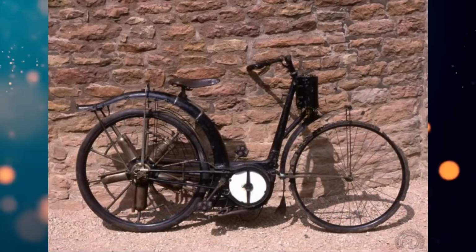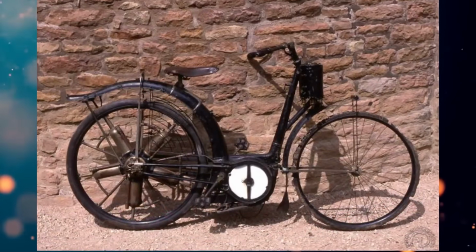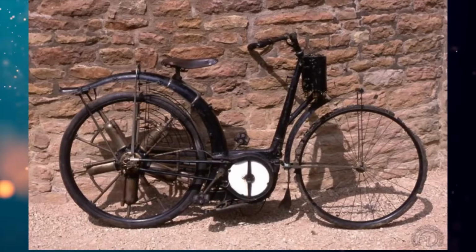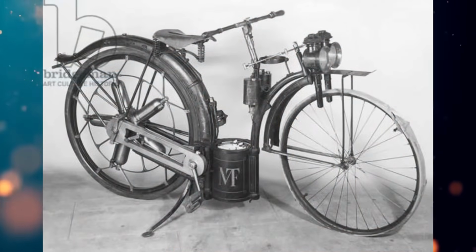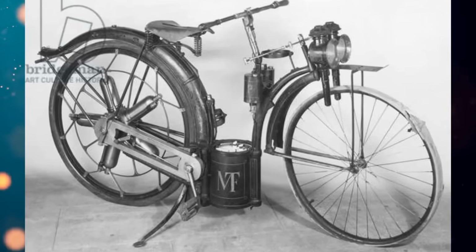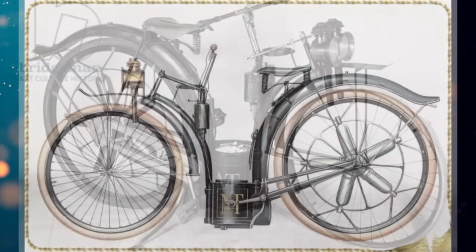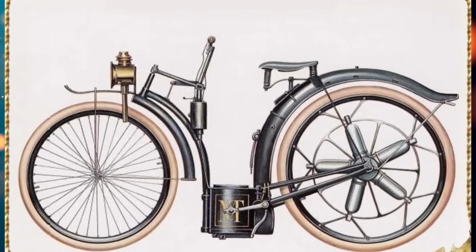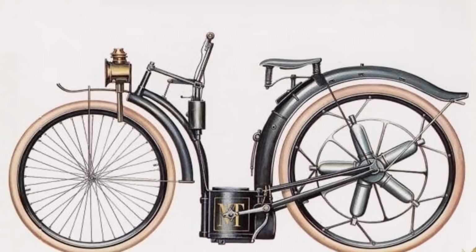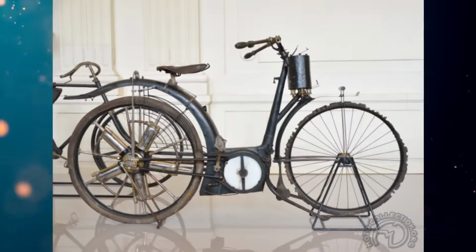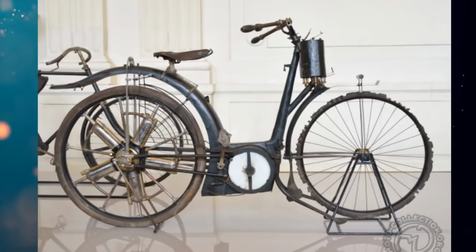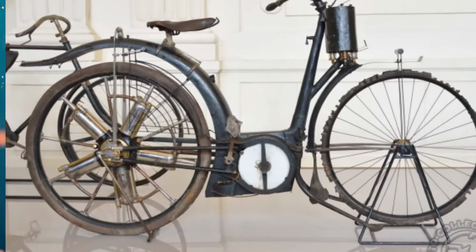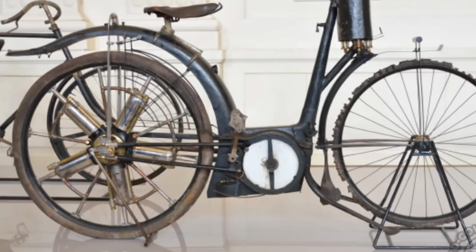The 5-cylinder unit, with a displacement of 1,925 cubic centimeters, produced a maximum of 1.2 horsepower at 360 revolutions per minute and allowed a speed of about 35 kilometers per hour. Fuel consumption was around 3 liters per 100 kilometers. The structure weighed about 60 kilograms, with the engine weighing 10. The rear wheel fender served as the fuel tank.